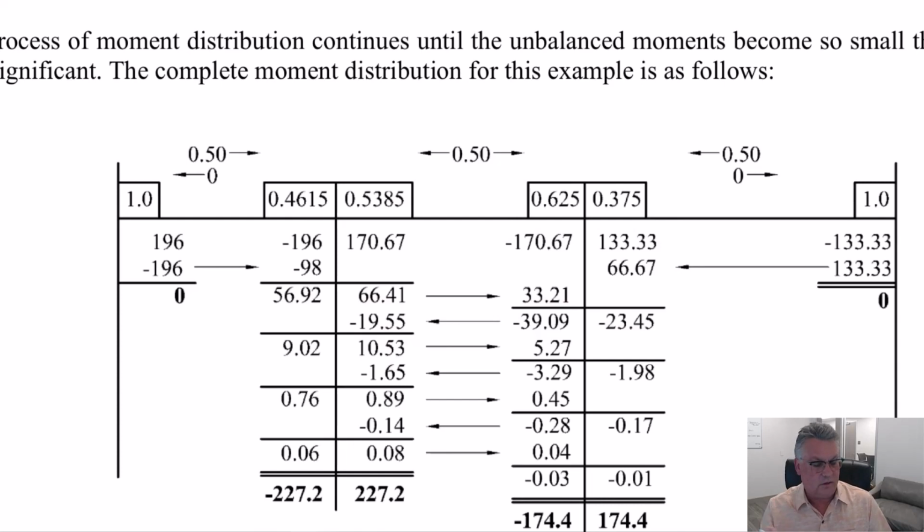I'm going to say something that's going to confuse you now. Even when we get to the project and you have columns introduced, those numbers won't necessarily add up to 0, but the point still will be that your joint was in equilibrium. You set it in equilibrium every time we go through a step. So the only way it's out of equilibrium is by whatever you sent over since it was put in equilibrium. So this 5.27 gets distributed a negative 62.5% here and 37.5% there.